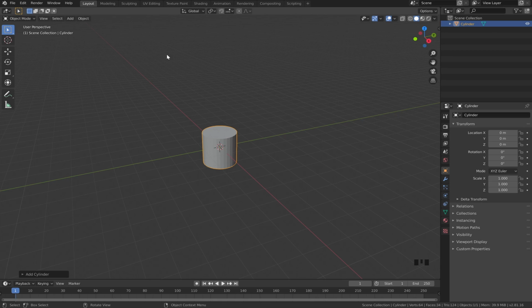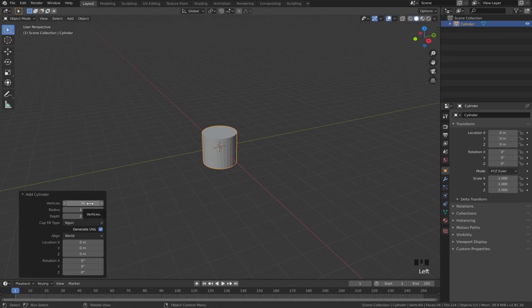You're better off in terms of quality smoothing it out compared to leaving it all flat-faced. It's more of a preferential thing, and it just makes it seem more high quality than just leaving it as flat faces. But we also don't need this amount of faces on a cylinder. We can always reduce it down, and smoothing allows that to happen. But we're not going to teach that right now, so just for future's sake, let's just trim this down.